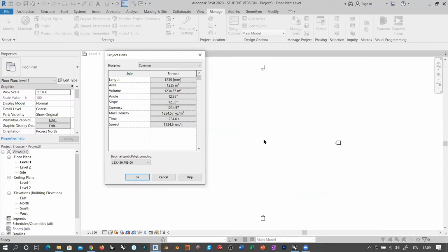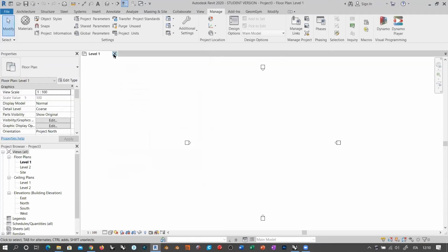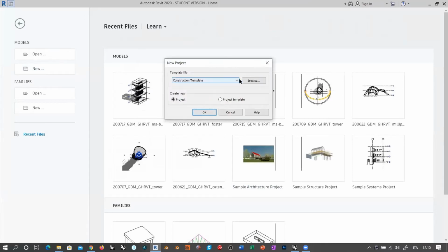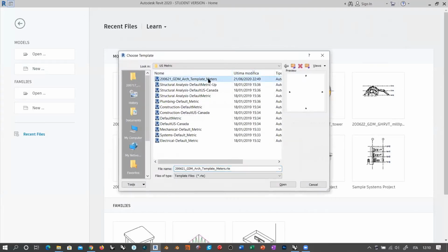So nothing appears. Normally the users tend to repeat the operation, thinking, I don't see the result. If I do it again, maybe it will show up. But no. The problem is with the scale. So if you see this behavior, it's because you didn't set the units properly. In my custom template, I just changed the units that you just saw into meters.